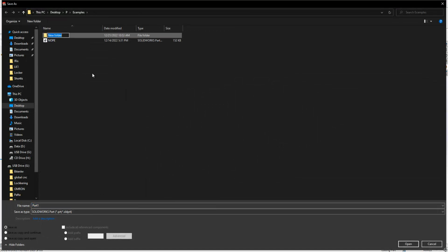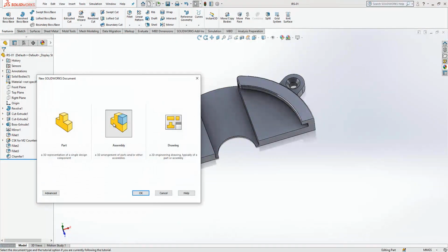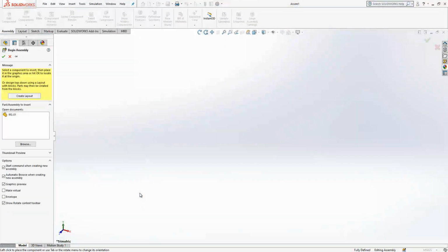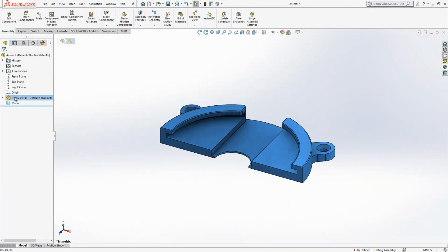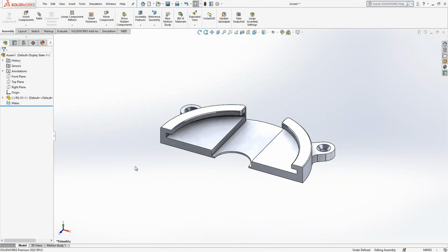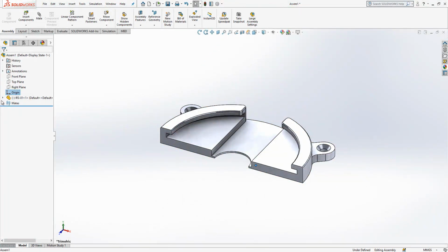I have seen examples. I don't know this part, but I will call it 2-blade iris mechanism. So I will call iris 01 the name of the part. So as I always do, I create my assembly also along the modeling. So I can here already start to complete my assembly. It is fixed and program randomly drop somewhere, but I want this thing to be constrained with my origin. So I will place it to origin.